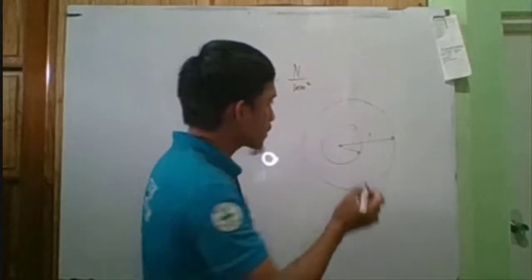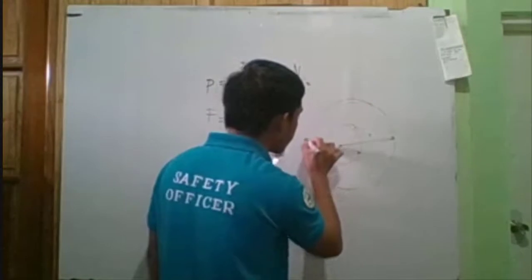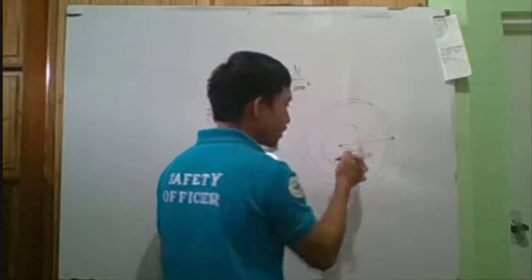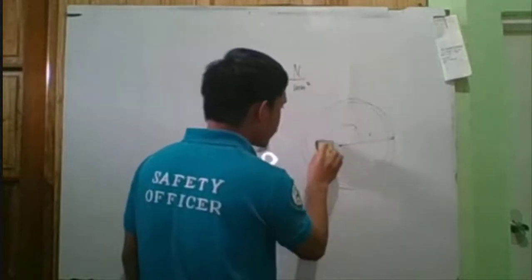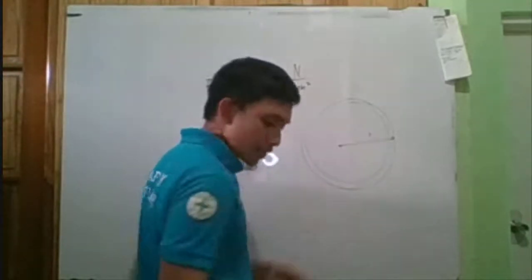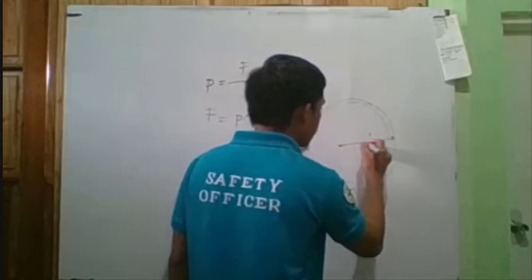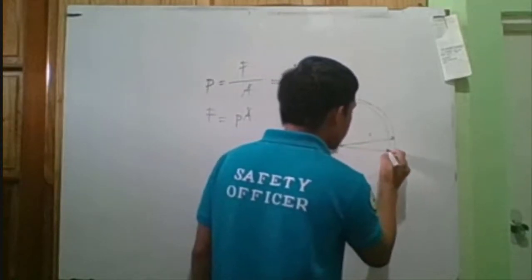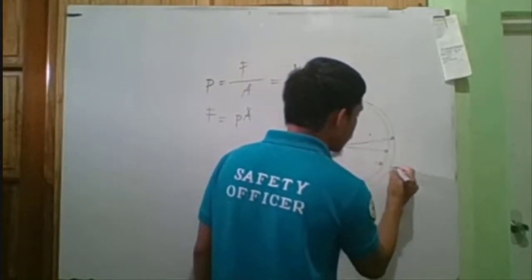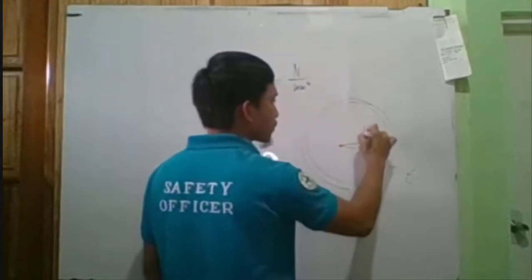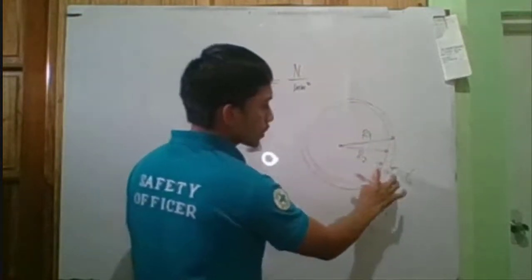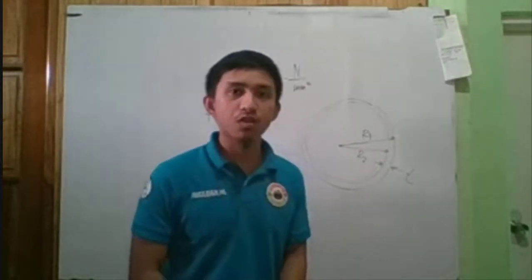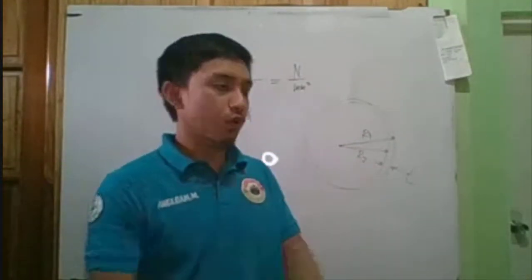But since the thickness is very, very small compared to the diameter, in ratio to diameter, this thickness T is very small. So R1, R2, if I subtract them, gives a very small thickness, which is common in thin wall. That's why we call this one thin wall vessels.